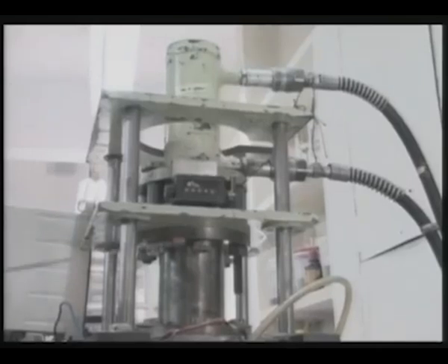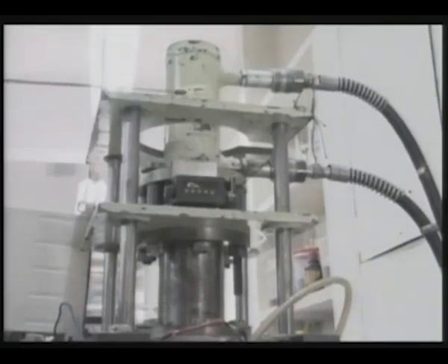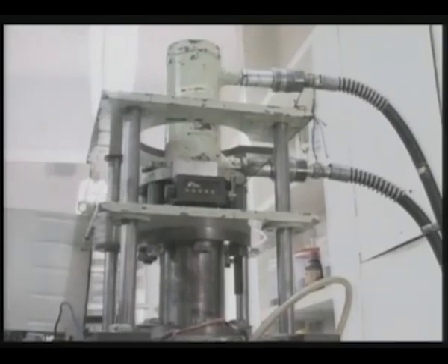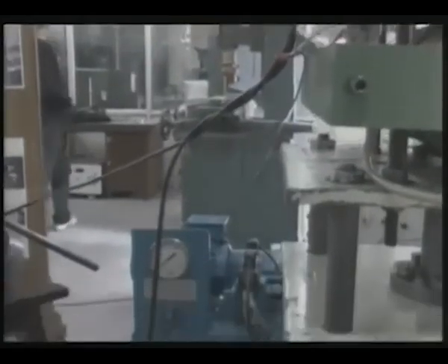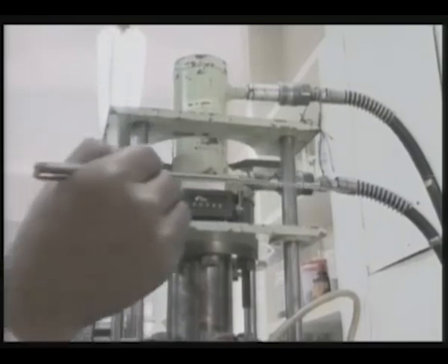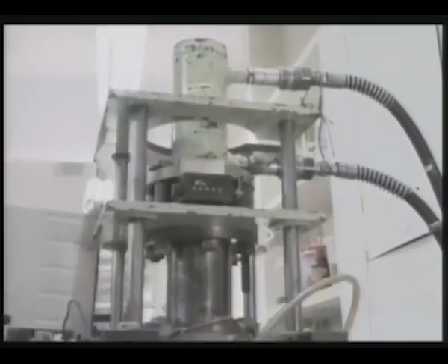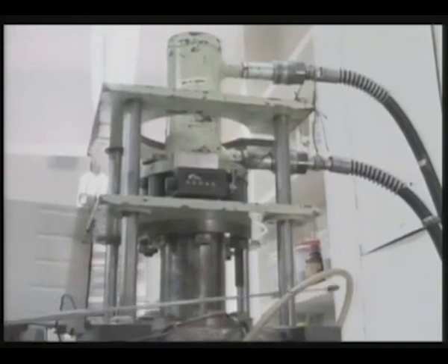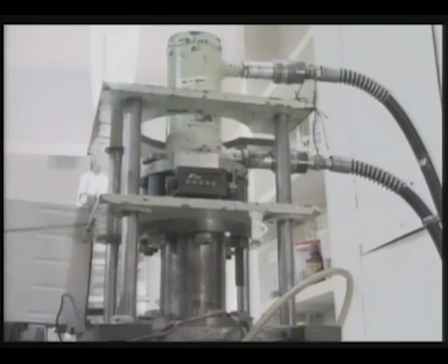This is the hydraulic cylinder and this is the media cylinder. Inside the hydraulic cylinder, one piston is there, and inside the media cylinder, one Teflon piston is there, and these two pistons are connected by a connecting rod. When the hydraulic pump is activated, the hydraulic fluid comes to the top entry of the pipe and presses the piston in the hydraulic cylinder, and the fluid comes back through the bottom pipe to the hydraulic unit. By this process, reciprocating motion is provided in the MRAFF process.